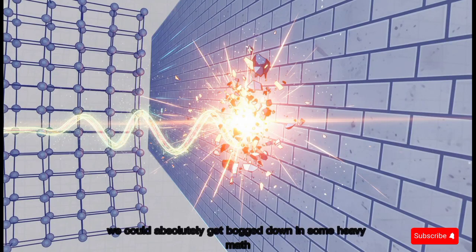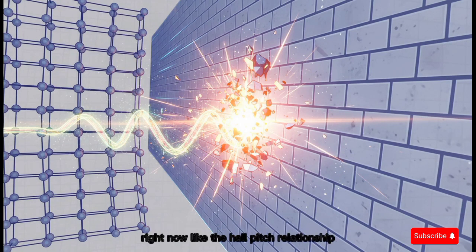Now, we could absolutely get bogged down in some heavy math right now, like the Hall-Petch relationship, but honestly, let's just visualize how this works. Think of these grain boundaries as solid brick walls. When those moving rug wrinkles or dislocations try to slide through the metal, they hit this mismatched wall and stop dead in their tracks. This brilliantly explains why creating materials with lots of smaller crystal grains and therefore way more boundaries actually makes a metal physically stronger and harder to bend.